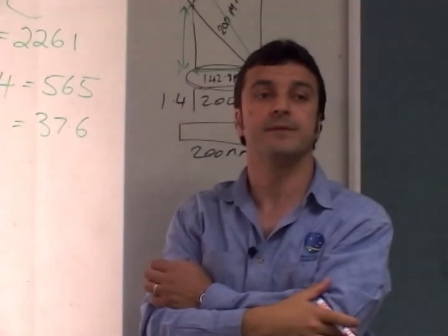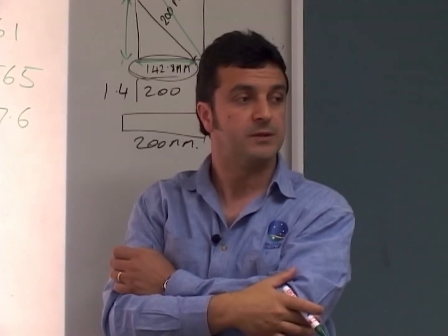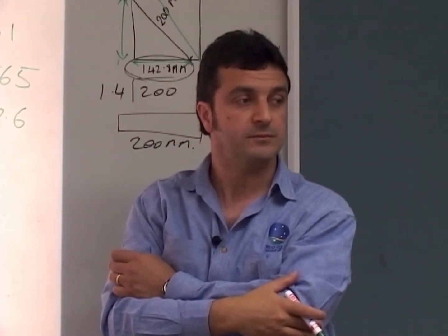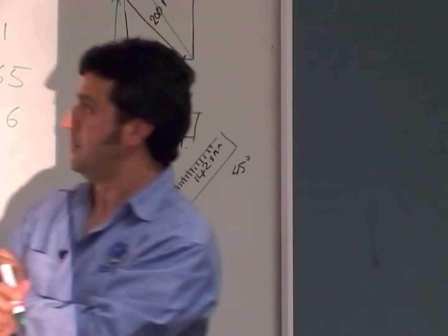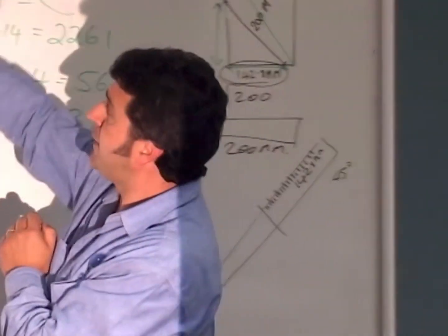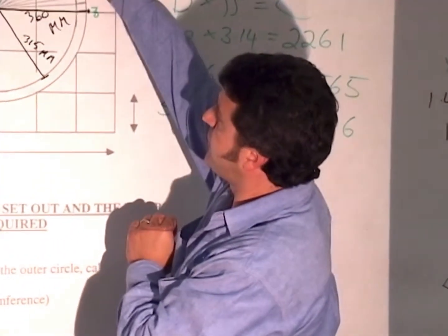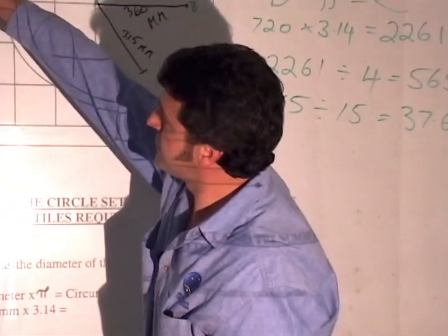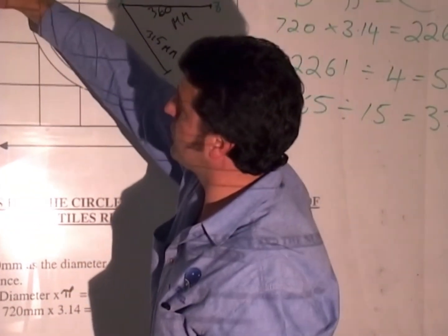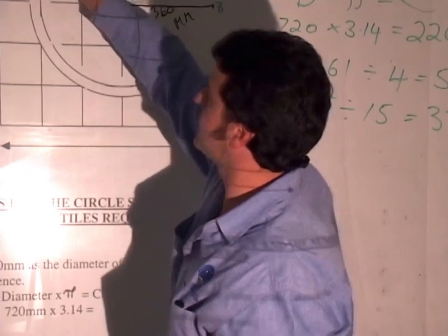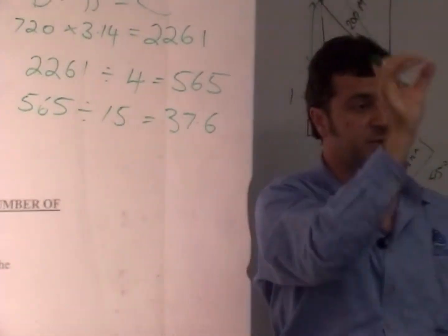Well, if you have to leave 45 on the top and bottom, how have you actually worked out to leave the joints between, or 15? Well, good question, Mark. I'll just finish that one off first. So if we take 2 millimetres at each end, it'll give us a balance of 41 millimetres. That's the size we're going to cut our strip.